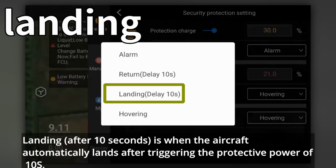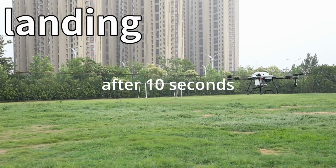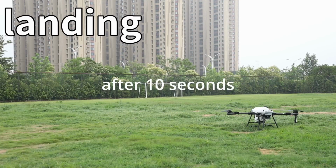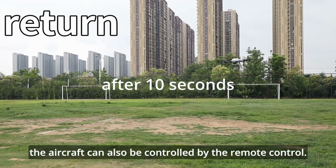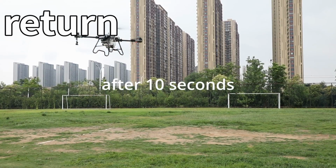Landing after 10 seconds is when the aircraft automatically lands 10 seconds after triggering the protection, and the aircraft can be controlled by the remote control at this time. Return flight after 10 seconds is when the aircraft automatically returns 10 seconds after triggering the battery protection. At this time, the aircraft can also be controlled by the remote control.